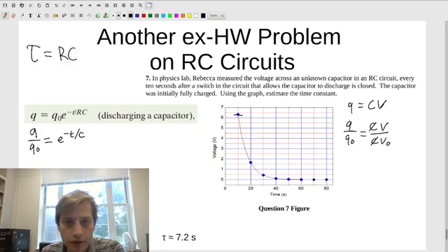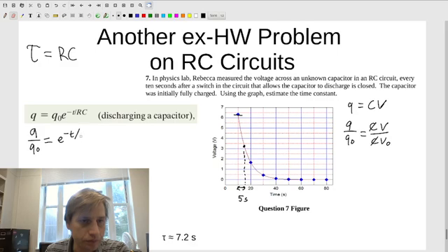So if we look here at voltages around maybe 6.4 volts. If we want to look, where do we get half of that? So around 3.2 volts, something like that. It looks to me like that's happening about like this. So this is 10 seconds. This looks about 15 seconds. It looks like the time it took for me to go from to 1/2 of the amount of current that I had was 5 seconds. Okay, so this should be tau.